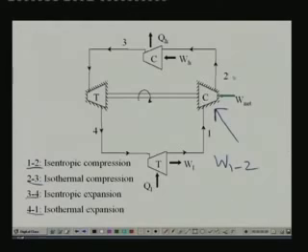Next, what happens is the gas, which is now at a high temperature and high pressure, undergoes what is known as an isothermal compression. You can see that process 2 to 3 is an isothermal compression. That means its temperature remains constant during the process, at the same time its pressure increases. This is a compression process, so you have to supply work input to the compressor.